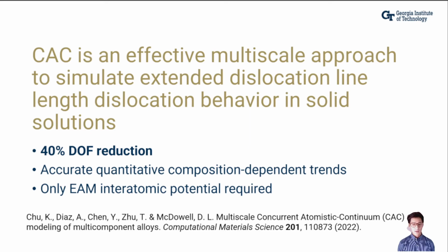In summary, CAC is an effective multi-scale approach to simulate extended dislocation line length in solid solutions. We do this with a 40% reduction in degrees of freedom, and we accurately quantify composition-dependent trends. The only thing required is an EAM interatomic potential for the alloy of interest. This work was recently accepted in Computational Materials Science, and the reference is here below for those interested.